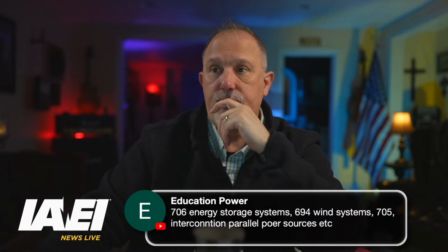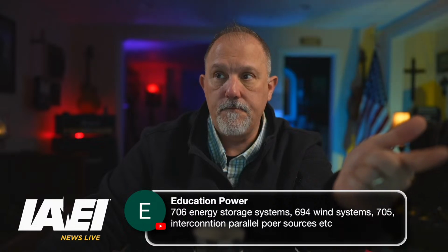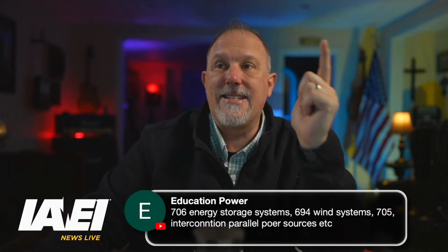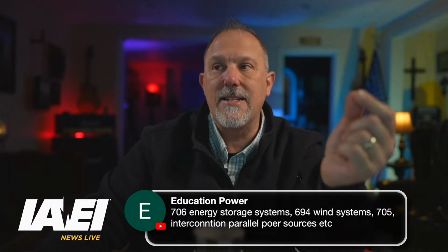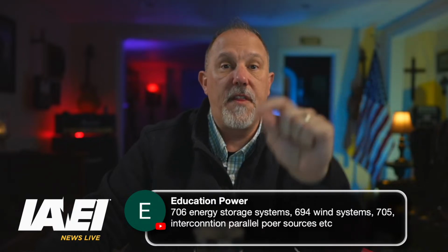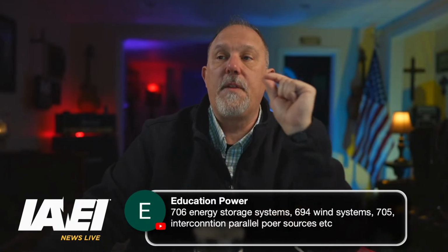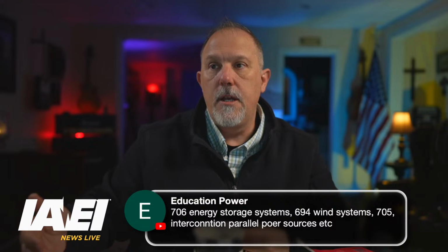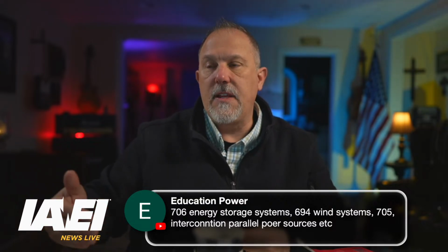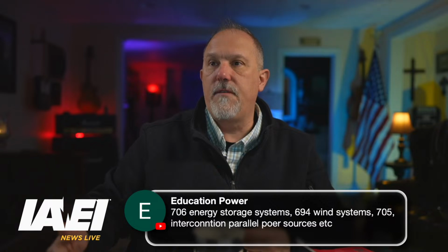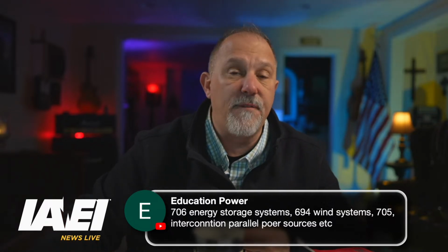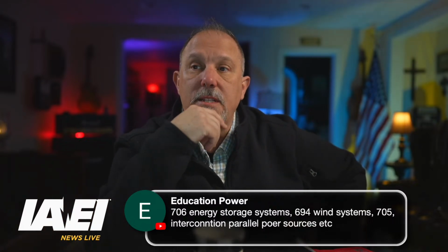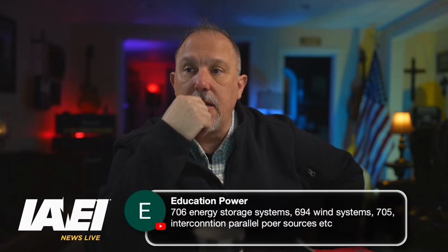You have a disconnecting means required. And it says, oh, I love this. The disconnecting means shall be readily accessible and shall comply with one or more. Located within the energy storage system, located within sight of, that's within 10 foot from the energy storage system. Where not located within sight of the ESS, the disconnecting means or the enclosure providing, and I'm reading from 706.15(B), shall be capable of being locked in accordance with 110. Where controls to activate the disconnecting means,